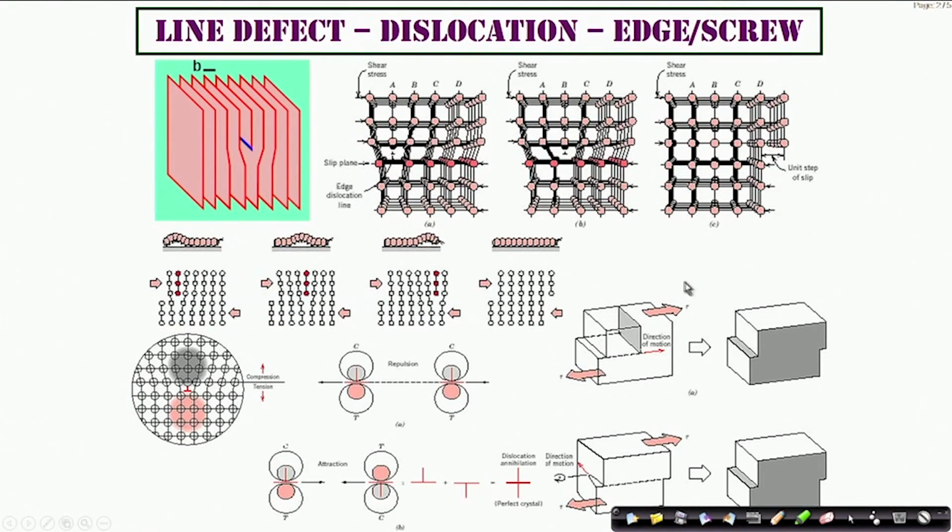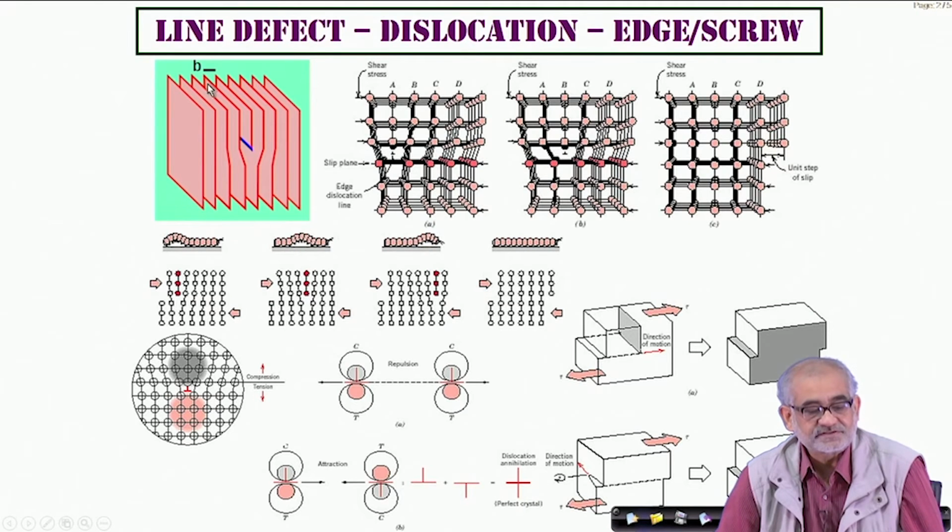So far we talked only about the point defects. Now what if you imagine a situation that we have these kind of planes which are equidistant because they are part of a crystal where we have long range periodicity, and for whatever reason, we also happen to discover an extra half plane introduced in between, sort of squeezed in between.